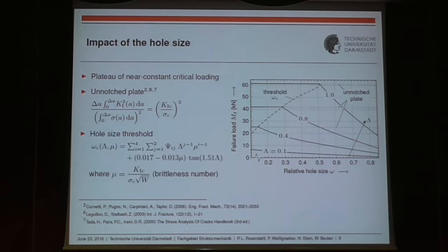And a pretty remarkable result of this work is that we can give this particular critical hole size as a function of the bending loading, obviously, but also the only second parameter that we need is the brittleness number. And this is a polynomial fit of fourth order. We have the coefficient matrix psi here. So we're a little astonished by this,